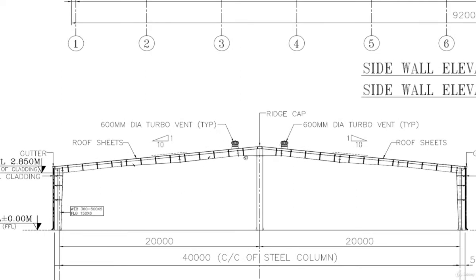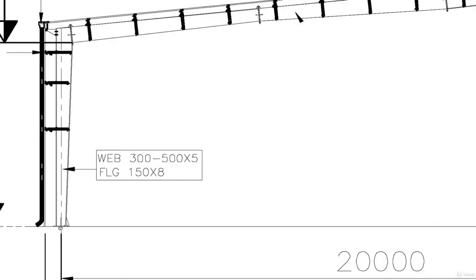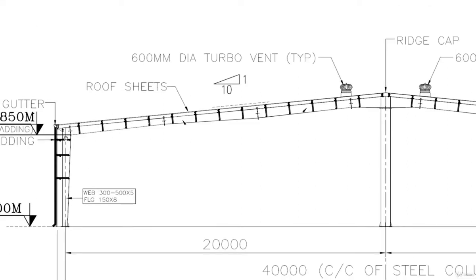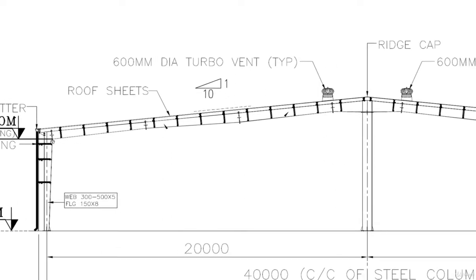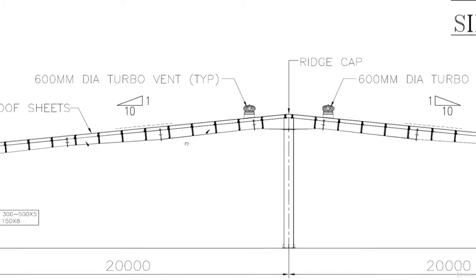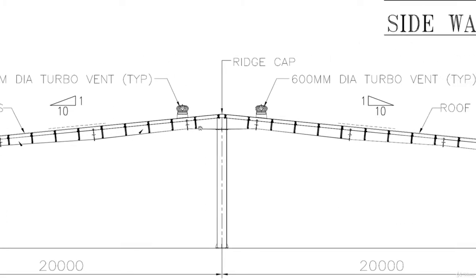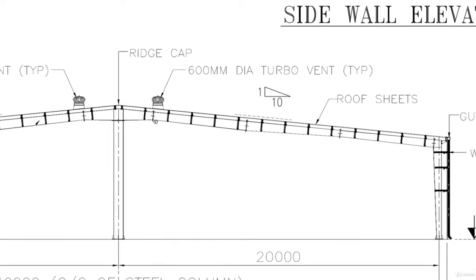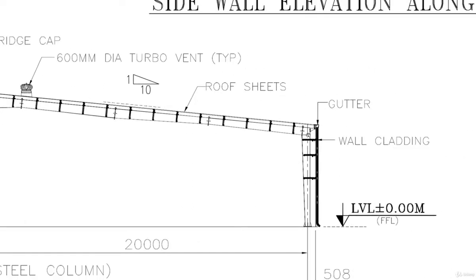Why I am showing you here is that we need to draw the PEB section property like this. That is, the property is continuously changing. The depth of the beam is low in the middle and high at the beam column junction. It again reduces here, again increases here, and then again reduces, and it remains constant for some distance. Here it is the same procedure: the depth is constant here, then increases, decreases, increases and decreases again.